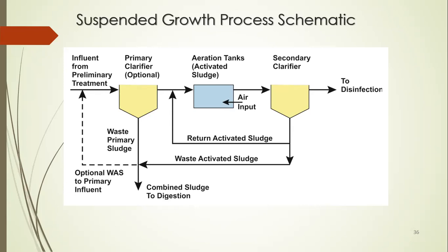So similarly, in the aeration tank, you have wastewater and the microorganisms together as a suspended liquid. What we will do is to enhance the biodegradation, you have to provide the right conditions. You have to provide sufficient oxygen.